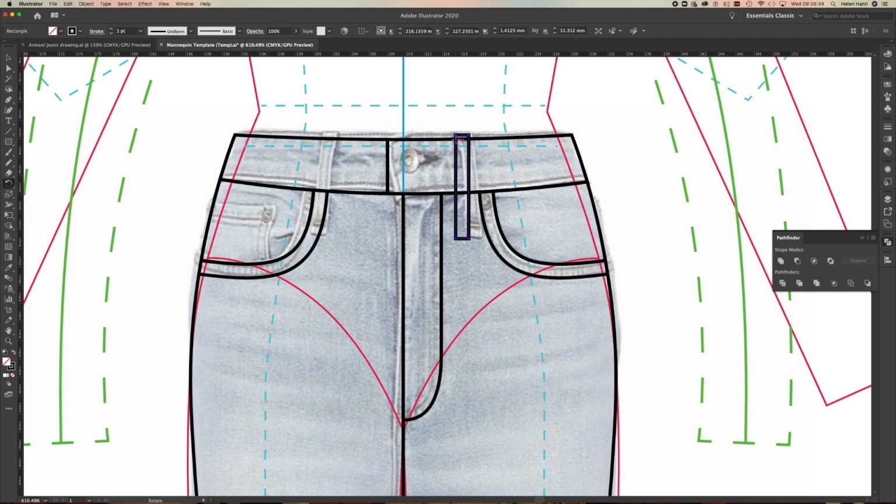I'm just going to put my point of origin down. So I'm going to anchor it here, if you like. It's like sticking a pin in, just there. Can you see where that little crosshair is? And then I'm just going to pick up this end here and rotate that into position. Once I've got the angle about right, I'm going to deselect and then reselect that shape, and then go back to my rotate tool.